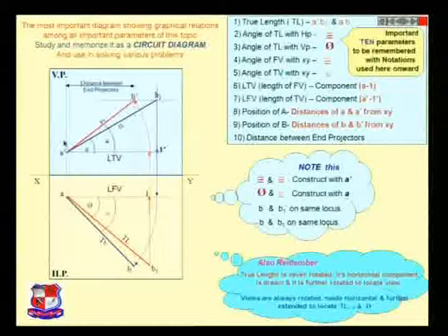This is our vertical plane. Always keep in mind that we have just unfolded the horizontal plane and vertical plane into a straight line. So the horizontal plane and the vertical plane would be in a straight line itself. The XY line differentiates the horizontal and vertical plane. Above the XY line is always the vertical plane, VP. Below the XY line, the HP component would always be there.